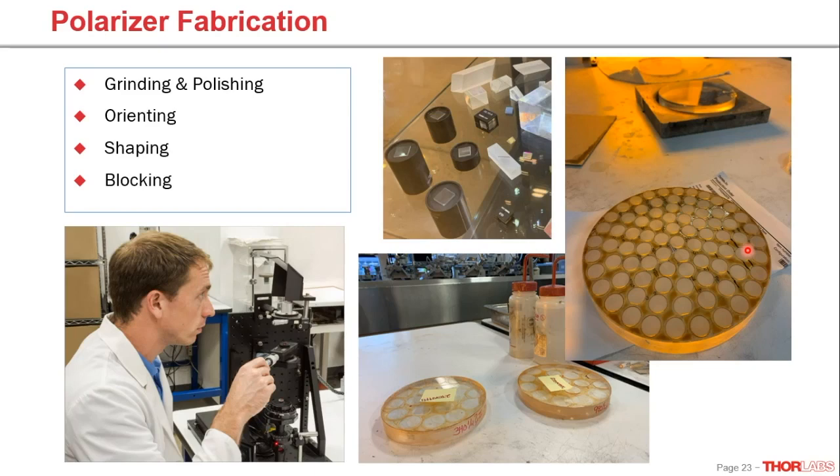In addition, that blocking technique is important to us because we actually employ methods that allow us to use no epoxy at those interfaces between the block and the optic. This allows us to maintain high levels of flatness, really critical levels of parallelism, and hold very tight levels of thickness as well, which is super critical on wave plates where we're talking about stuff on the order of optical waves in terms of accuracy that we need to maintain for the part to behave similarly across the entire aperture of this part. And we do this.